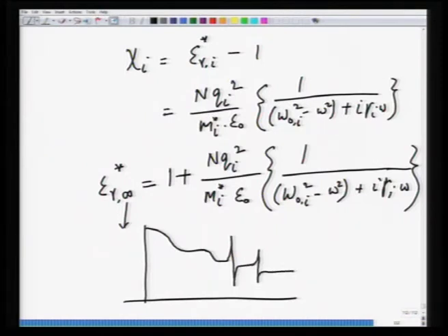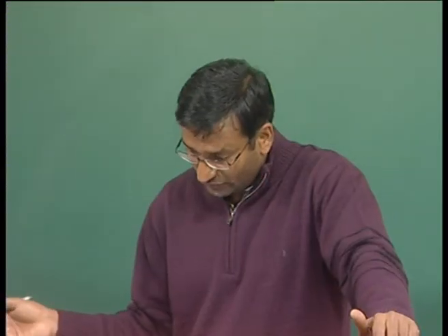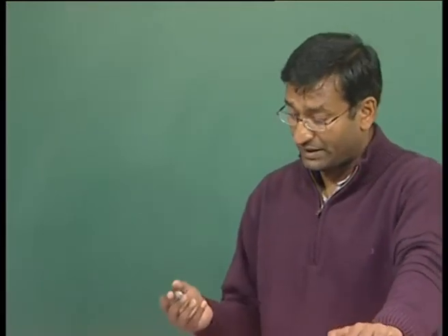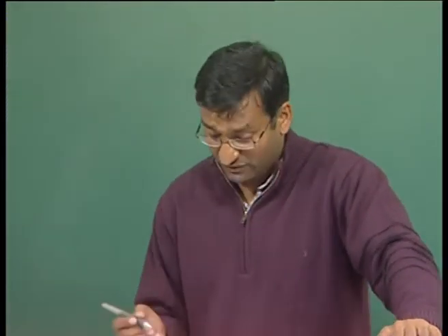Like that. So, these are the resonance frequencies, and so we are taking this range in which the dielectric constant is flattish or static. Okay. So, now from this you can see that epsilon r has a dependence upon the frequency. Now, the question is how can we separate the real and imaginary parts of the dielectric constant.